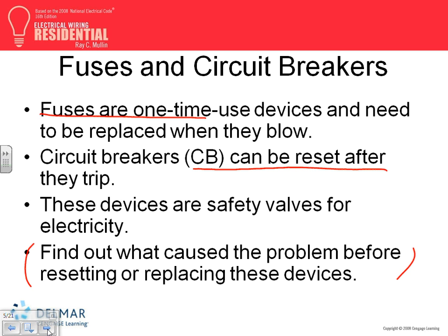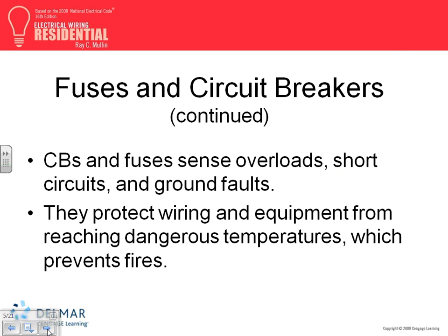If it's a 2000 amp circuit breaker and you close it on a short circuit, you're going to see a huge amount of energy hitting. It might hurt. It might damage your hand as you close it. It could blow right in your hand as you close it on a short circuit. Big deal, guys. In a 15, 20, 30, 40, 50 amp circuit, not a big deal. Nobody gets hurt.